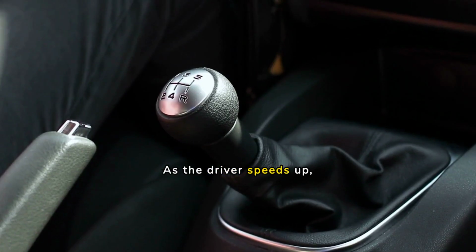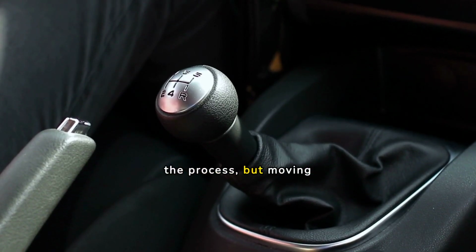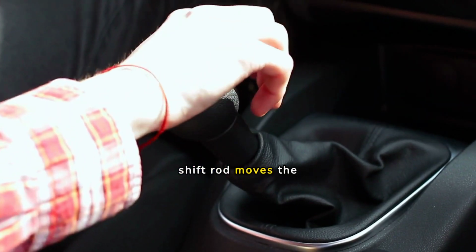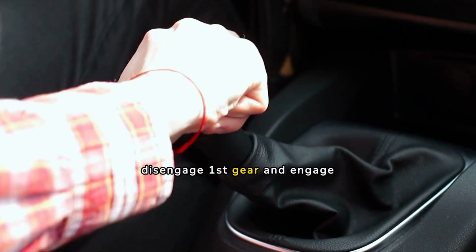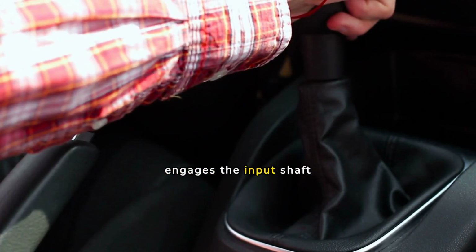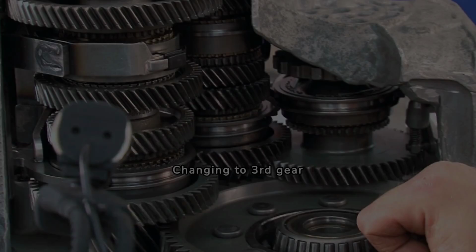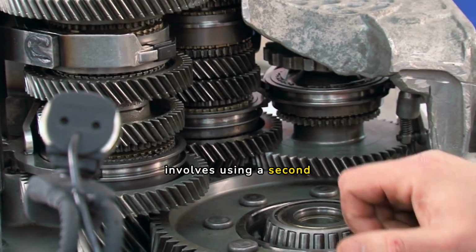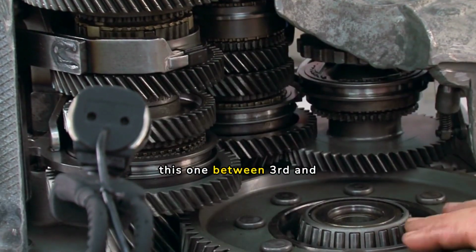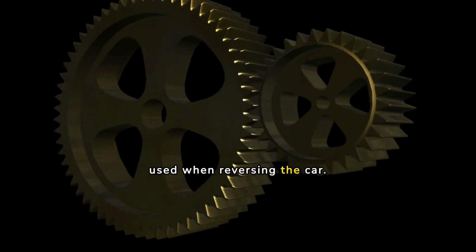As the driver speeds up, selecting second gear simply involves repeating the process, but moving the shift lever to second gear. The shift rod moves the shift fork to disengage first gear and engage second gear. Releasing the clutch engages the input shaft again, this time routing power through second gear. Changing to third gear involves using a second shift rod, shift fork, and synchronizer, this one between third and fourth gears. The idler gear is used when reversing the car.